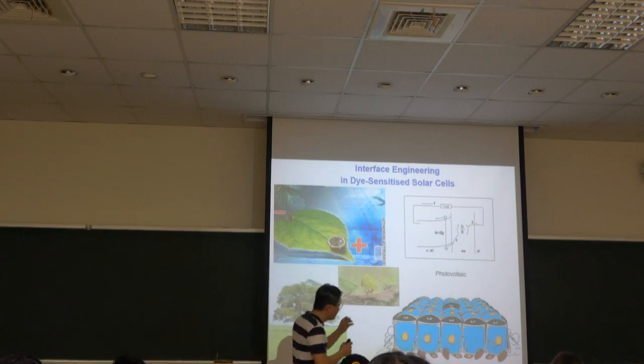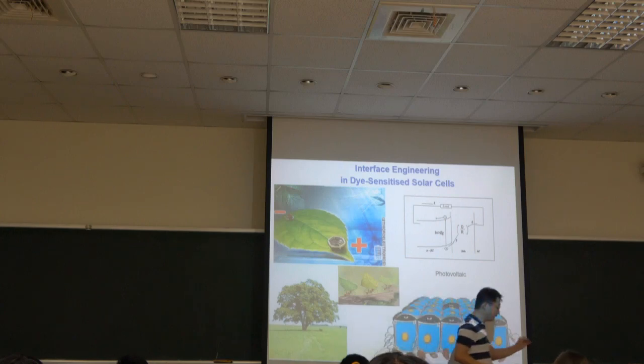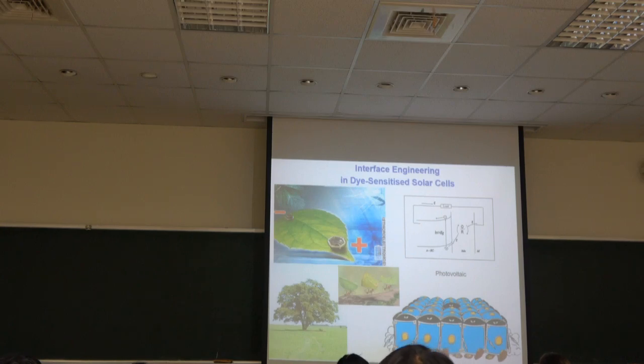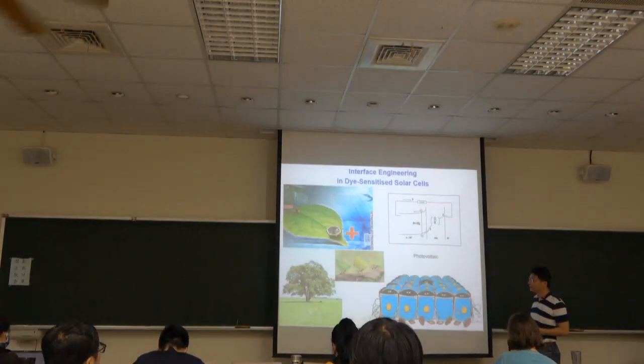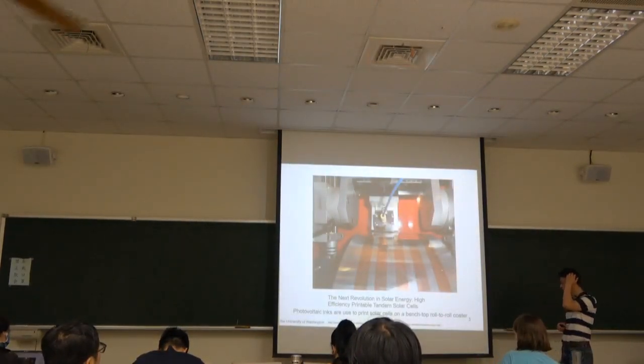Dye-sensitized solar cell means that we have small nanoparticles, maybe less than 50 nanometers, 20 nanometers, and each particle can photo-generate electron-hole pair separation. If we can do good preparation to get a good current collector, we can convert to a high efficiency photovoltaic solar cell.